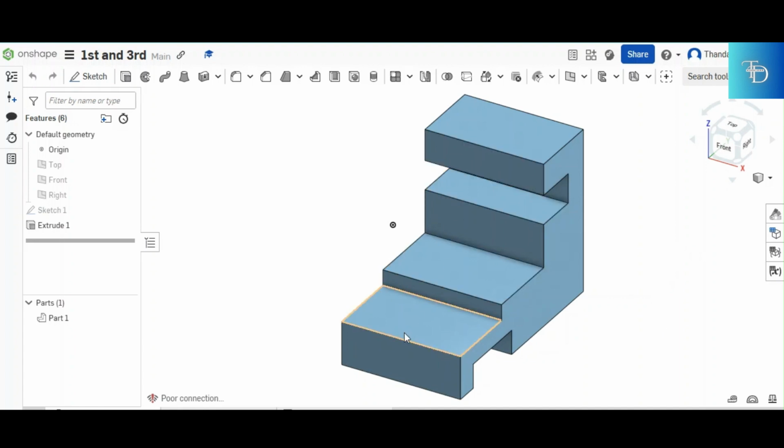Because this is still your front, yes? Because this is a third angle now, we are no longer showing the left view. We're going to have to show the right view. And since this is the front view right there, the right hand side of the front view is this side right here. So this is the right view now, right there. The top doesn't change. The top is still the top.